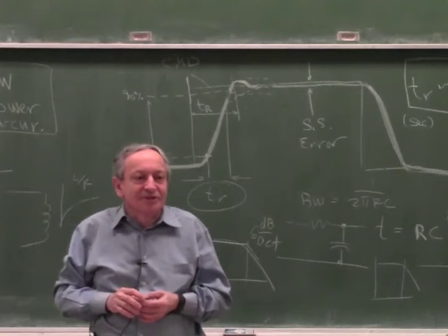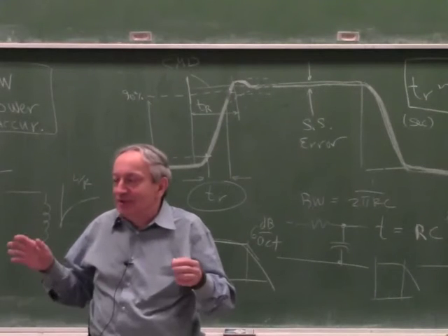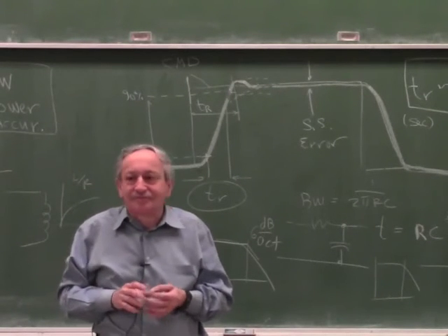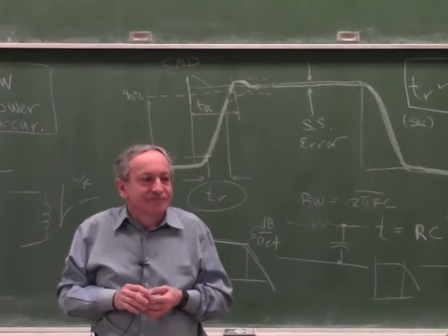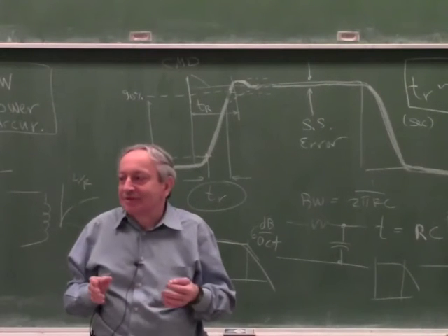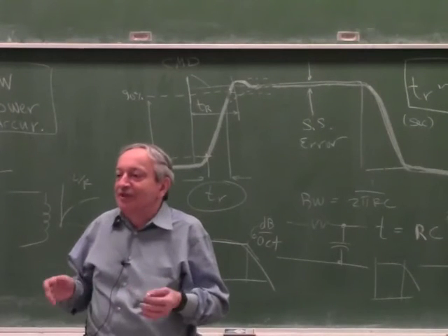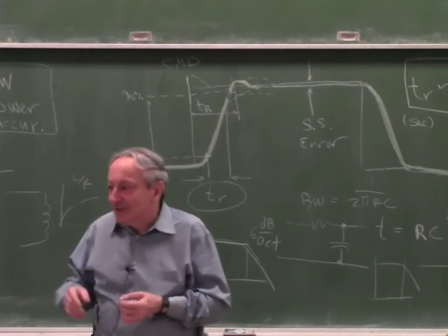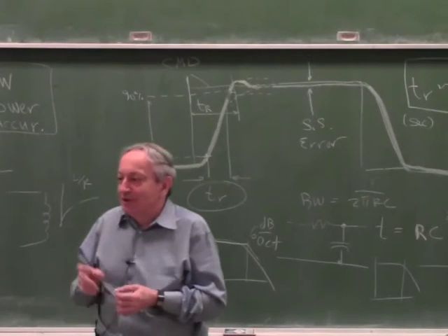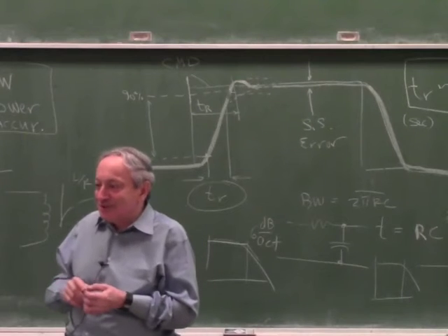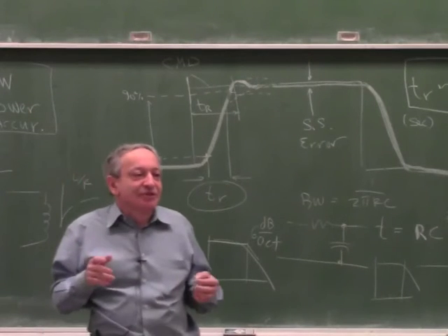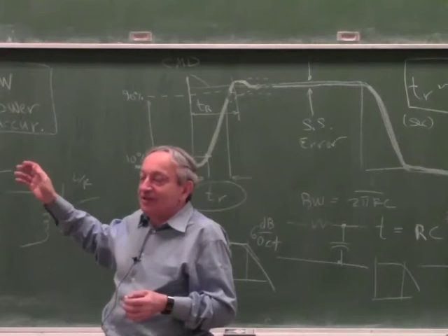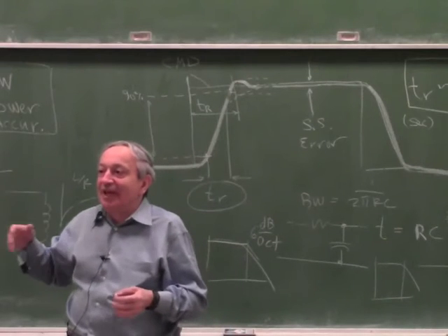So there's two reasons, which again we spent a week on. So, why does a servo system need a filter at all? Aliasing. Yes, pardon? Aliasing, very good. How come only you remembered? So there's two reasons. One reason, most servo systems are digital today. You're going into an A to D converter. If you don't put a filter, there will be aliasing.